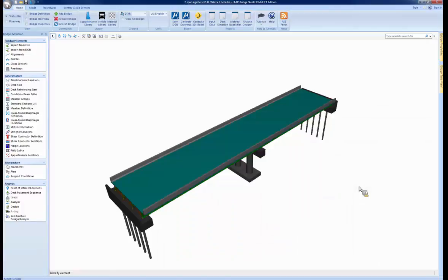Okay, another question. Does the optimization work for curved steel girders as well? Yes, it does. We do pick up on those differences in force effects that are reflected in the code checking, and one of the equations mentioned, the value we use when computing those web depths, depended on whether it was a straight or curved structure. So yes, we are accounting for those.